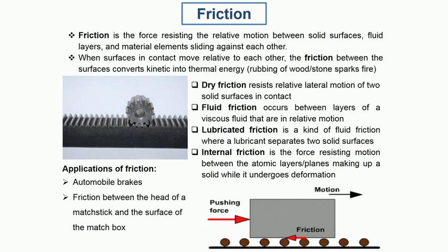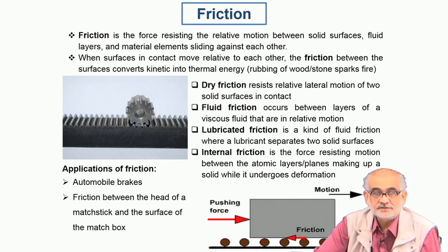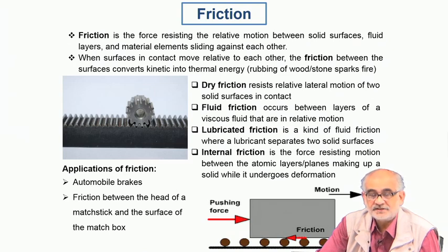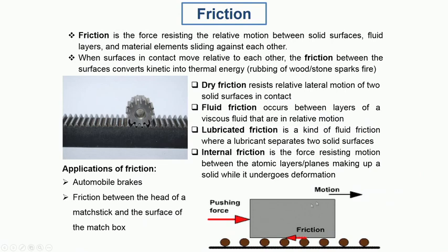So unless we apply sufficient load, convert it into stress, convert it into shear stress on a particular section or plane, which is enough for a dislocation to move, unless we cross that threshold, the so-called critical resolved shear stress, there will be no motion of dislocation, and we would say that the internal friction is so high that we are unable to deform.